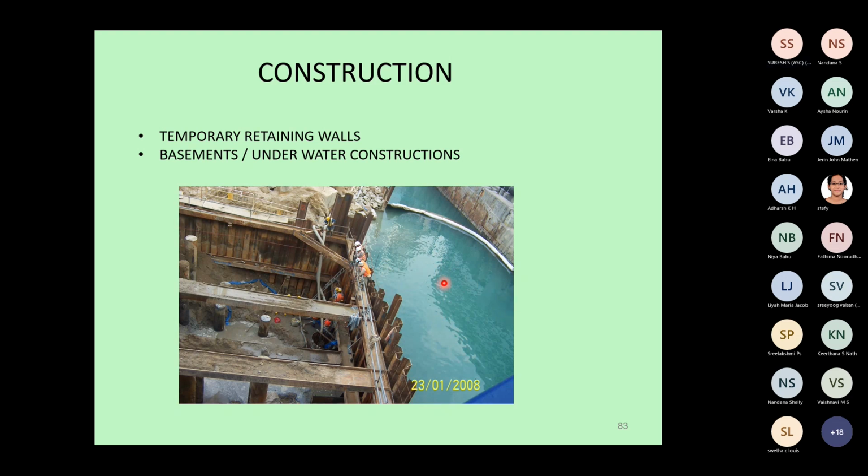This is the Hong Kong Sea coming very close to the structure, and we are digging almost 5 to 6 meters below the sea level. The people who work here are around 5 to 6 meters below the sea level. So they protect the seawater coming in to work in this foundation by providing a temporary wall, temporary caisson or temporary sheet pile wall. And to prevent its collapse, they use strutting inside, diagonal strutting, cross strutting, things like that.